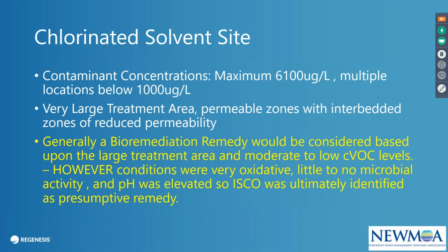Interestingly enough, at this particular site, on the chlorinated solvent side, normally if I looked at a site that had concentrations, say up to 6 ppm, but quite a large area had less than a part per million, I'd be looking at this as bioremediation, no question. But at this site, the conditions are so oxidative, it was almost impossible. Not a lot, no bugs, just nothing. And Rich will describe some of the conditions in a lot more detail.